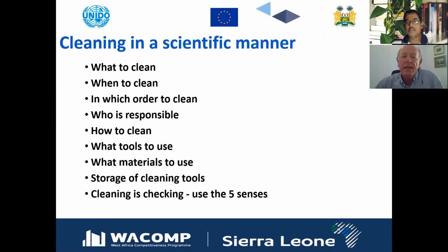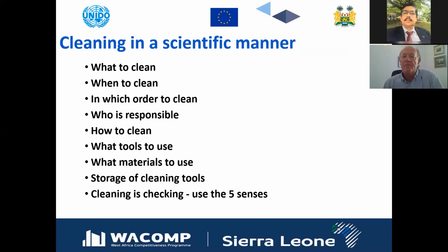We need to clean in a scientific manner. We're not, like I said, just talking about shining things. We're talking about cleaning as a means of identifying potential problems in our equipment. So we need to think about, what do we need to clean? It may be something like the filters in the air conditioning unit in our office. Do we need to clean those every day? Probably not. Do we need to clean them once a week? Probably not. They could probably be cleaned monthly.